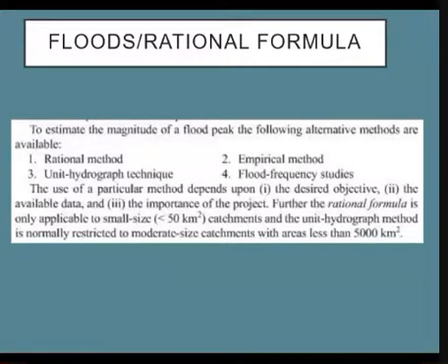Further, the rational formula is only applicable to small size catchments, less than 50 kilometers squared, and the unit hydrograph method is normally restricted to moderate size catchments with areas less than 5,000 kilometers squared.